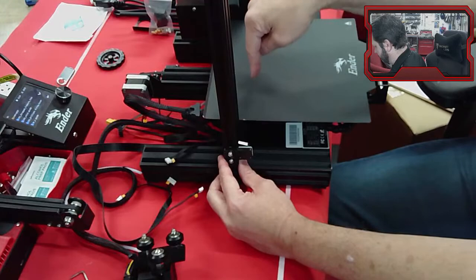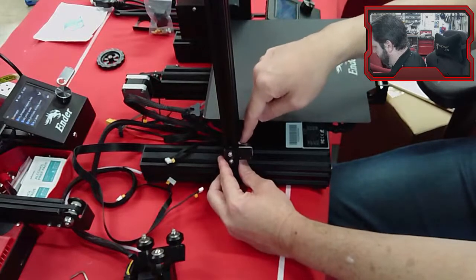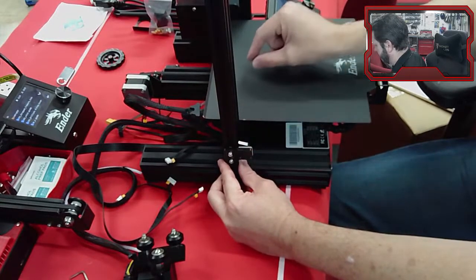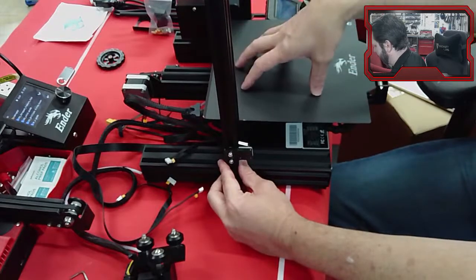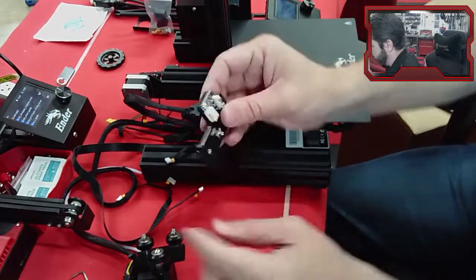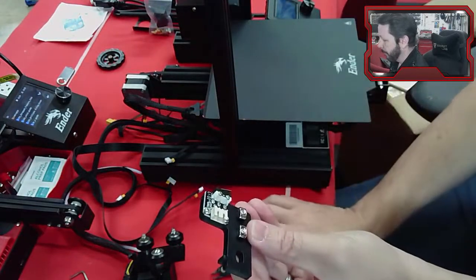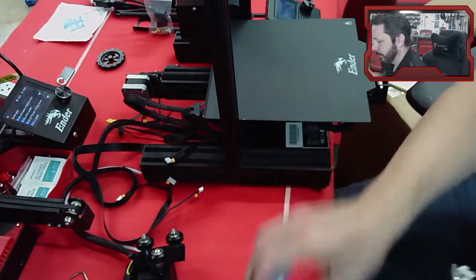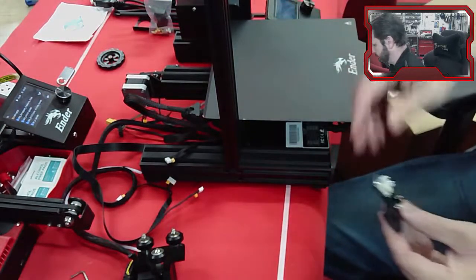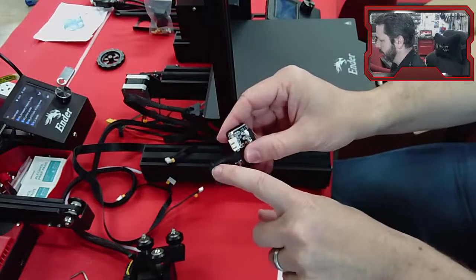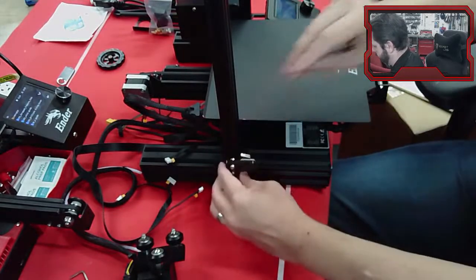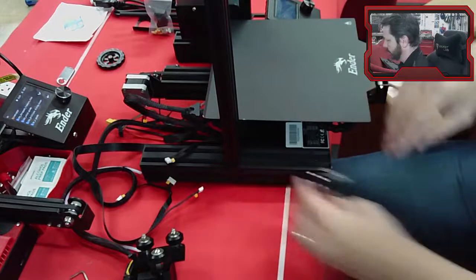In other words, where it triggers at its lowest setting, the nozzle is too far above the bed and it can't reach the bed. Then what you do is you take your little nippers and you cut that little piece off. I will leave it on there and see if it's set correctly for this printer, but on all the ones in the past I've had to cut that little piece off so that I could move this to more positions.